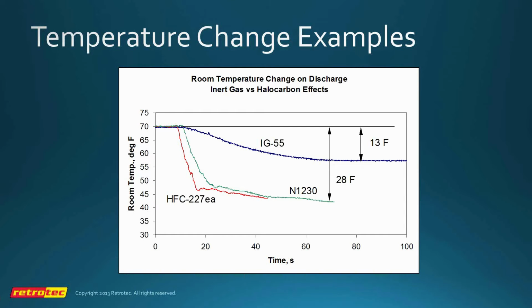So the mistake that we've made in the past when evaluating peak pressure is we're looking at it as a pure flow rate formula. In fact, it's really a thermodynamics issue where we've got agent being blown into the enclosure, we've got cooling going on, we've got all kinds of effects happening, so it's not simply just a flow rate, Bernoulli's theorem, etc., with air blowing through a hole and so forth.